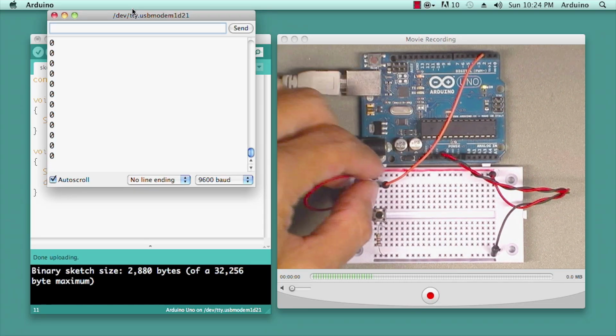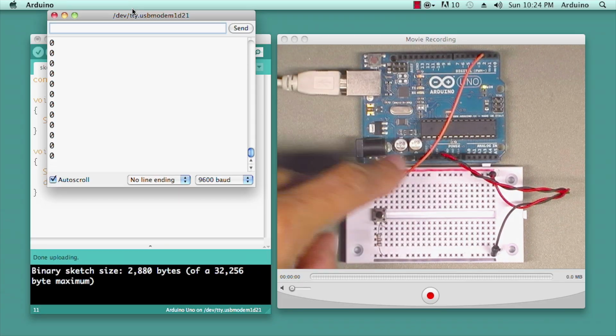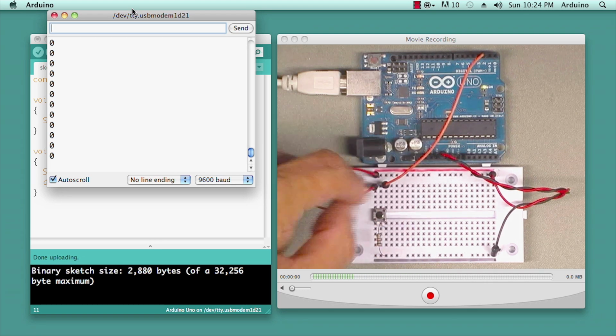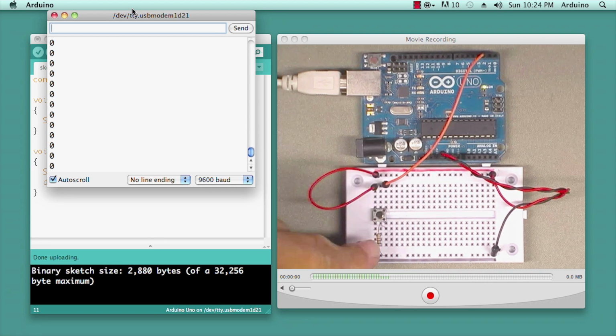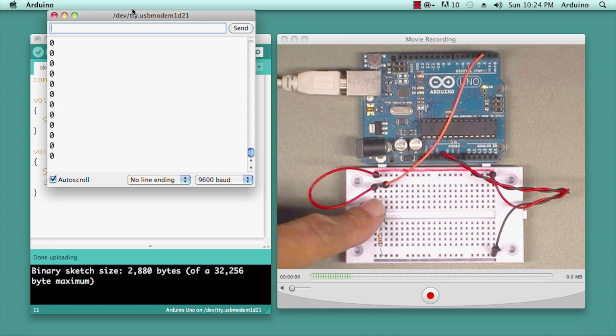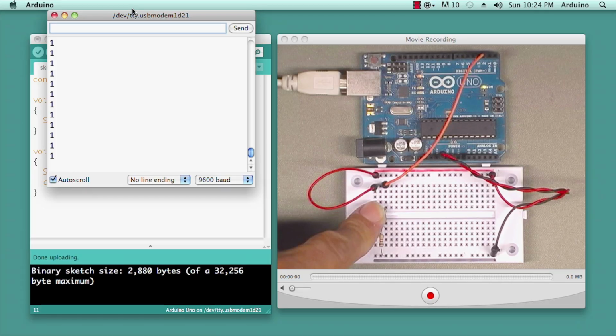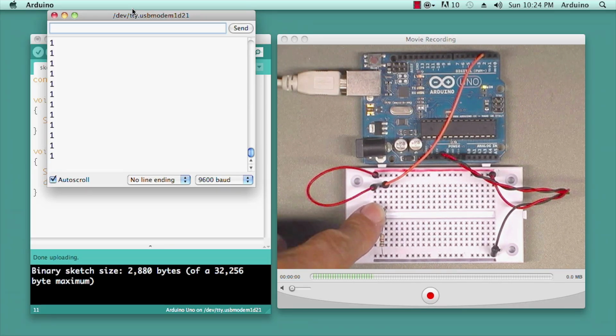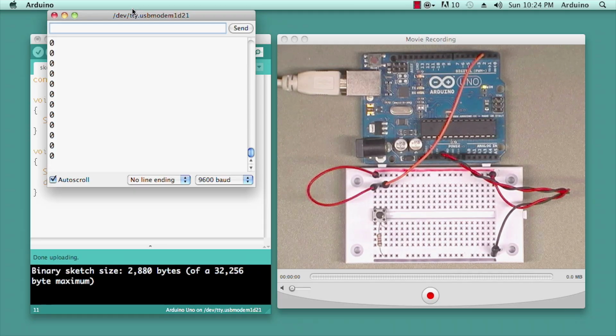I'm touching the wires, always 0. Because now my body with its capacitance is offering way more resistance out here in the open air than this 10K resistor. So this is always the path of least resistance until there's an even better one through the switch to power. And that is how we handle a digital input.